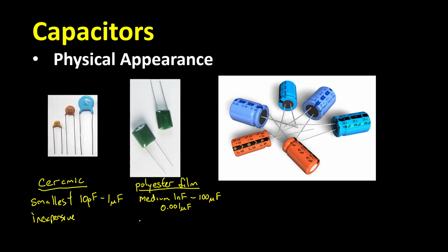Now these are somewhat inexpensive. These are bipolar, and so are ceramics. And by bipolar, I mean that there is no preferred positive side. They can be placed in either way. In fact, they look perfectly symmetric. And that's different than the largest of these, the electrolytics.